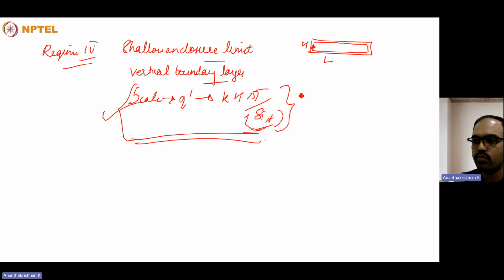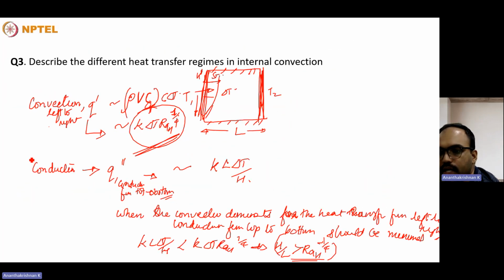In the core region, the two branches of the counterflow make good thermal contact, rendering the counterflow an effective insulation in the left to right direction. So as and when the fluid gets heated up, it moves towards the colder plate and then comes back, but the inner region of the core will remain unaffected by this flow. So that completes the third question.